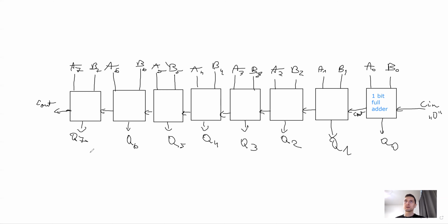Do you understand this concept? You can write in chat, yeah, it's simple, or I don't really get it. It's simple, you say. Okay, you're smart people. So this thing is called, for example, an 8-bit ripple adder. And yeah, it has a special name. Now, my question to you is, how many taus do we have to wait until we get the last Q?